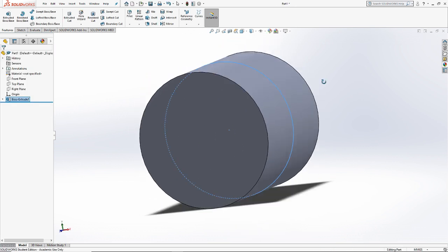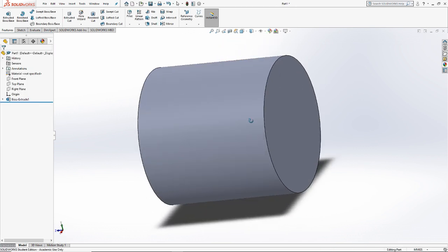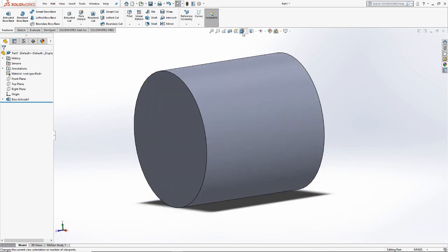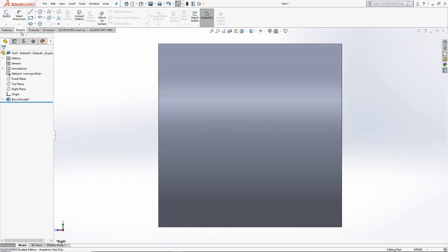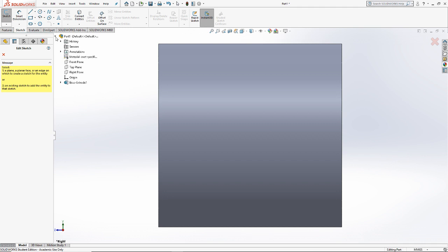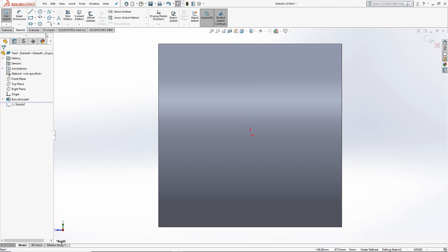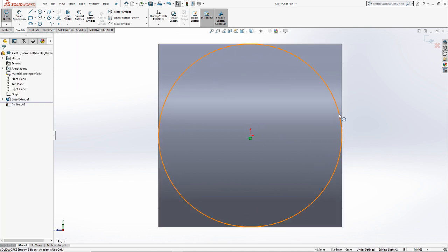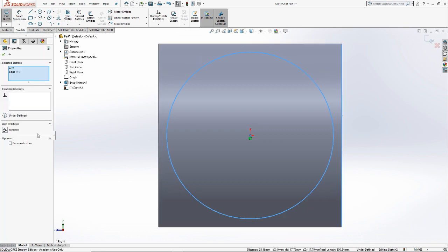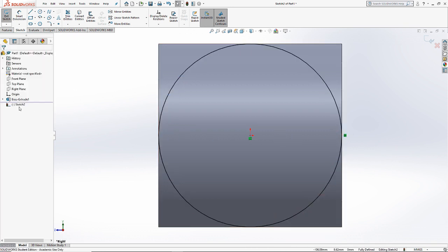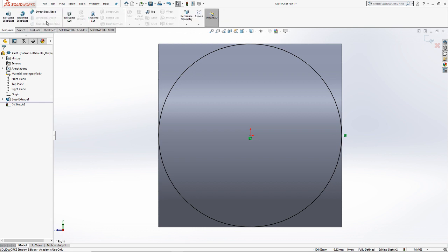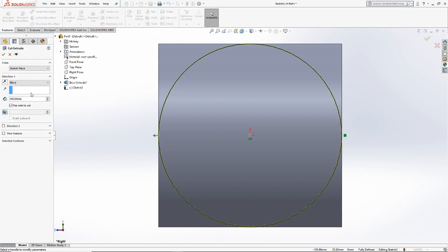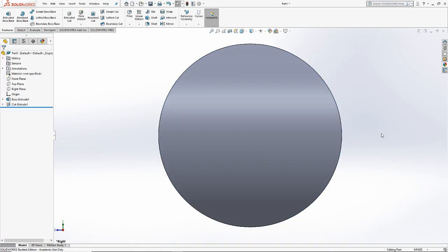Oh, wait, no, that's not a sphere. Okay, I got this. Guys, don't worry, I got this. I can cut it from the right side. I'll just draw a circle, and then I'll cut around that. John showed us last time how we can cut around a shape, so I'll do the same thing again. I'll make a circle, I'll put the origin in the center, I'll put the outside edge tangent to one of the surfaces because I define that as being 100 millimeters across, therefore the circle will have a diameter of 100 millimeters. And then I'll go up to Features, I'll go to Extruded Cut, and then I'll cut everything around the circle. I want to flip side to cut, I want to cut through everything in both directions, and now we have a sphere, right? Oh, look at our beautiful sphere.